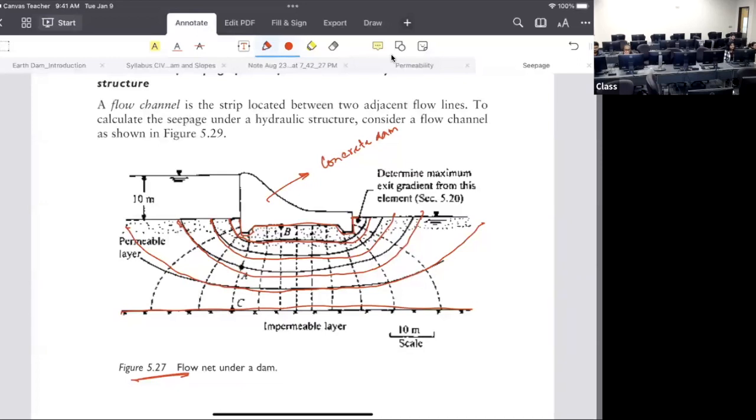Then what is the second idea? Your equipotential drops should cut the flow line at right angles. Right? So what is your starting point? Here. It goes like this and coming here, coming here, coming here, perpendicular, all perpendicular, equal. If you consider it equal like this, so I get it.